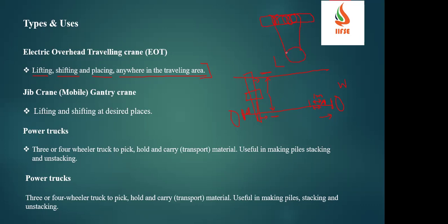And here we have the roller, and for this we have a hook. So here we have a sensor. Unless the hook comes to this position, it will be okay. Once it reaches this maximum height, it hits the height limit switch, also called limit control, or generally the limit switch in industries. Once it comes here, it will stop the winding function, so that we can avoid over winding of this drum.